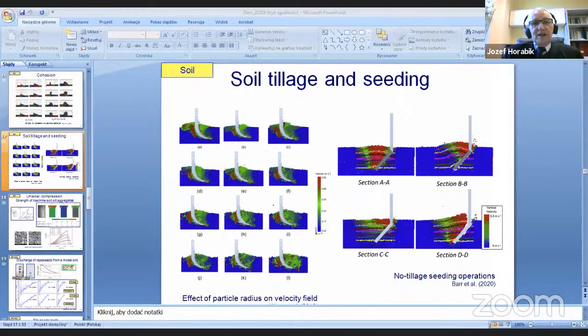Another example, handling of materials and bruise damage of apples. Schaffer et al. showed that bruise damage of apples during repeated impact loading can be effectively modeled with use of the viscoelastic contact model and the multi-sphere method. Bruise volume increases almost linearly with the peak force exerted on that particle.